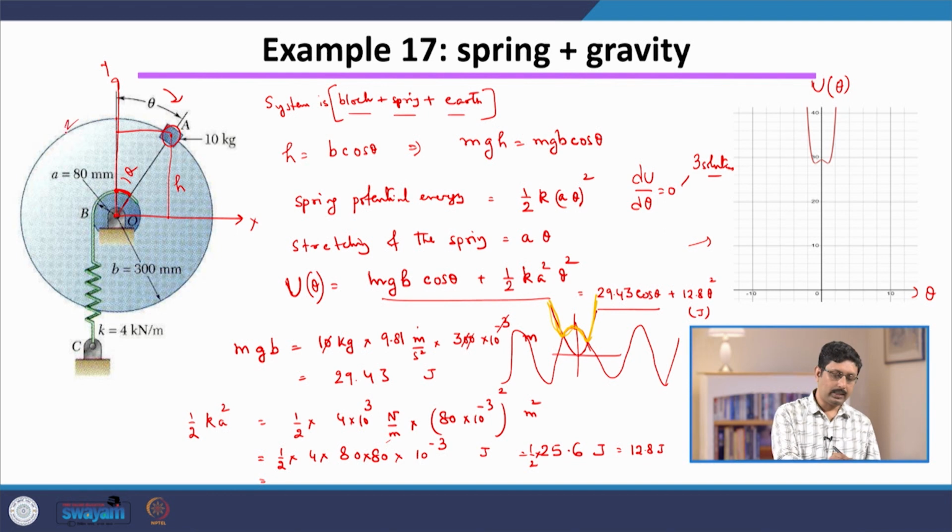Similarly, on the other side, if it starts to fall on the left hand side, then the spring is going to compress and the spring will not like it, so it will try to stretch itself. So, again the net effect is to try to prevent the fall of the block. Initially the spring force will be small, and as the angle theta increases it becomes stronger and stronger.